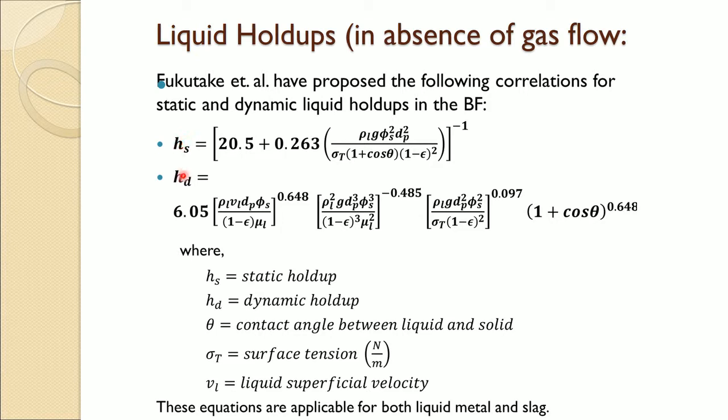Once you add these two, static and dynamic, you can know the total liquid hold up, and you can modify your void fraction of the packed bed, and then you can calculate the gas velocity and liquid velocity, because that is important in calculation of heat and mass transfer, which are going to be affected by these two parameters, and that is why they are very important.